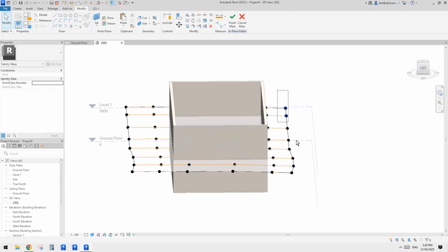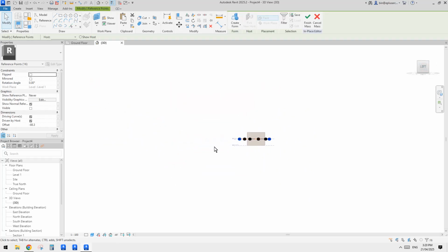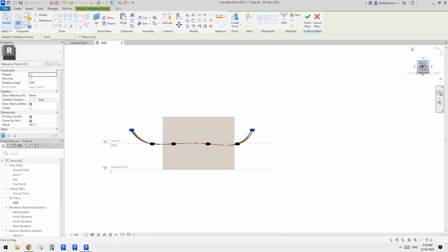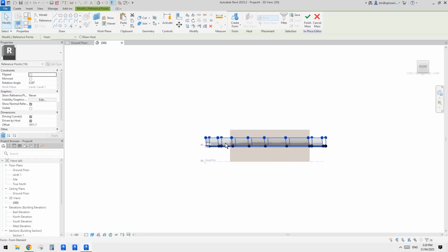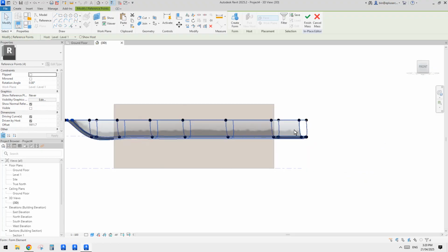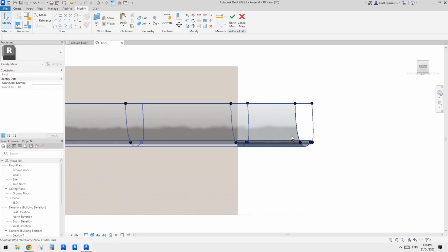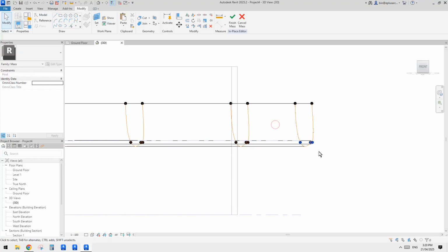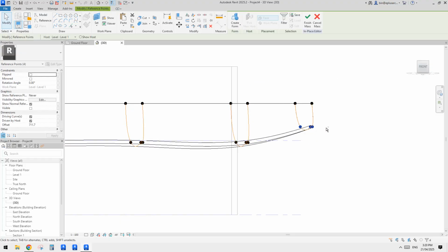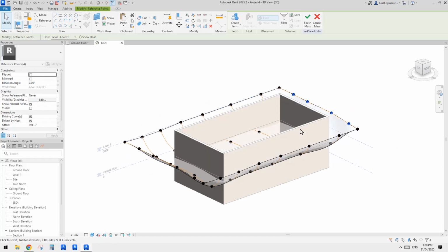Let's try again. Maybe just move these 2 sides first, right? And go to the other side, and maybe select these, go up, and select these. Maybe I'll use WF wireframe, so I won't accidentally pick that, and move them up. Okay, so now let's change to shaded, SD.